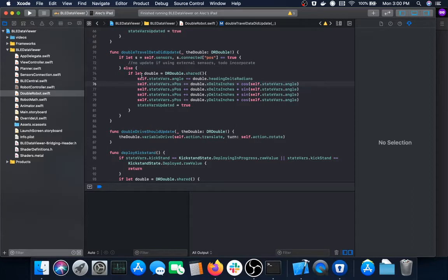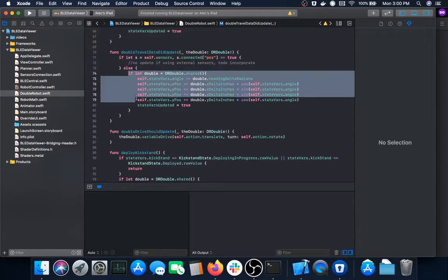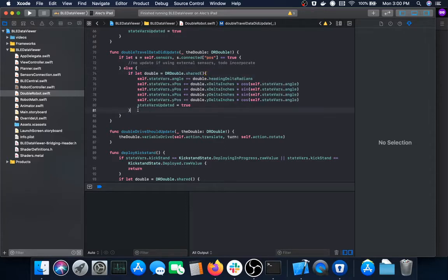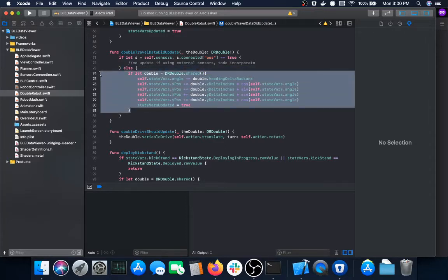Ultimately this was not accurate enough, just using the encoders and integrating the state change from the encoder values. It was not accurate enough to get a really high quality position for even a few feet, and the angle was always pretty far off, maybe even by a few tens of degrees.